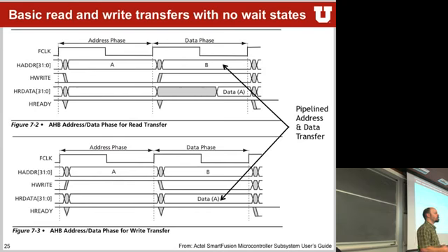If you have to read a peripheral that's slow, in your case, you said an ADC, yes. Or if you, for example, have to read out a flash memory, the flash memory is not fast enough sometimes. It cannot keep up with the speed of your bus. So what the peripheral has to do is wait for a couple of clock ticks until the data has been read out of your flash memory and put back onto the bus. So wait states get added if a peripheral can't keep up with the master clock itself.